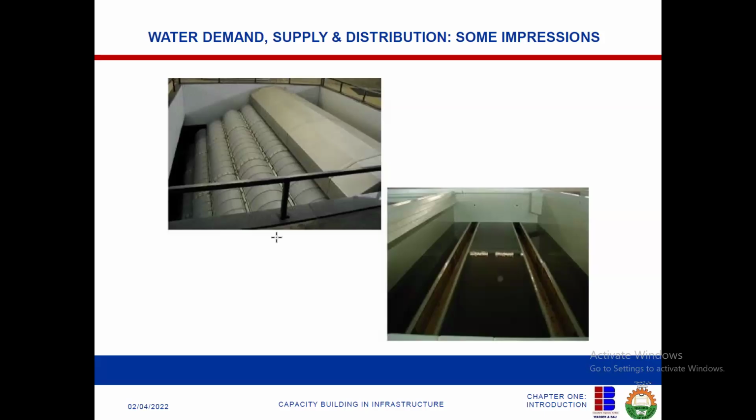This is a typical aerator used in the water treatment plant. What the aerator does is aerate the water, because the basic methodology of treating water is to aerate it, to introduce oxygen. What does oxygen do? The major mineral element in water is iron. Most times it is iron or silica, or a mixture. It's a combination of iron and other mineral elements.